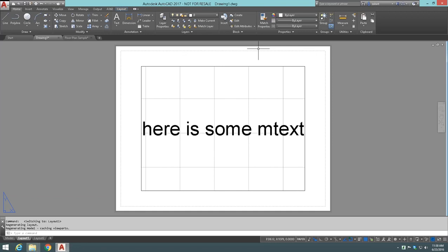Right, batch plotting I also see there in the question. Thanks, Dan. Batch plotting, publishing, batch plotting and publishing, same thing. Type in publish, you get the batch plot dialog. Or if you hover over the button that says batch plot now in the ribbon, you'll notice the pop-up says publish is the command you're executing. So it's the same thing. And you're right, Naman, there definitely are other webinars that cover those, in much greater detail than we have time for today.